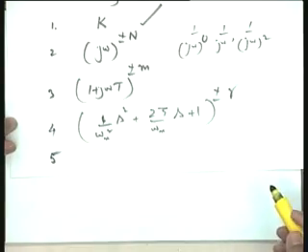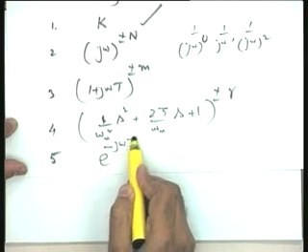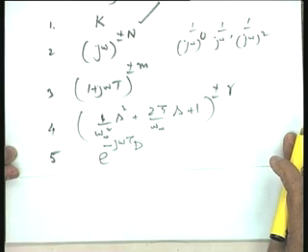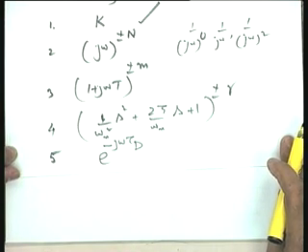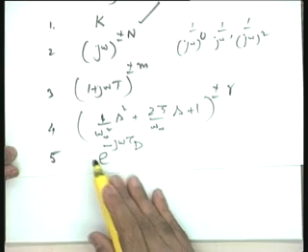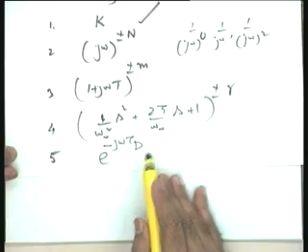Anything which I missed, which you think you may come across as far as the Bode plot construction is concerned? Anything which I have missed, please do help me. There could be something. Let me list it here. Yes, I could list here probably the delay also, e to the power of minus j omega tau d. I told you in process control systems the delay is quite frequently available, and therefore, this in our models may come quite often, and therefore, let me take this also as a building block, e to the power of minus j omega tau d, where tau d is the delay.